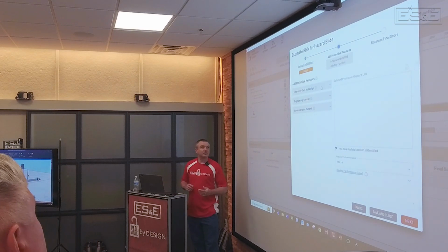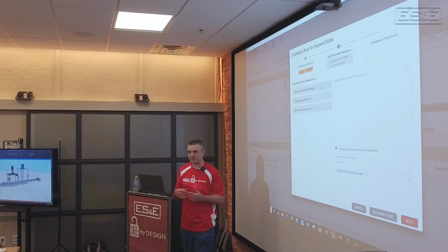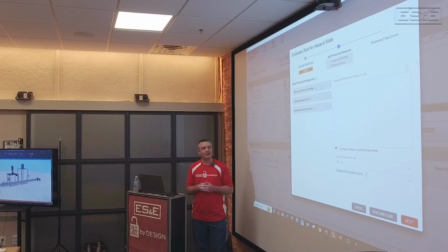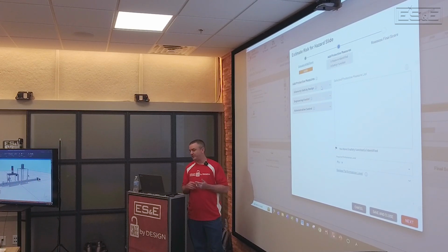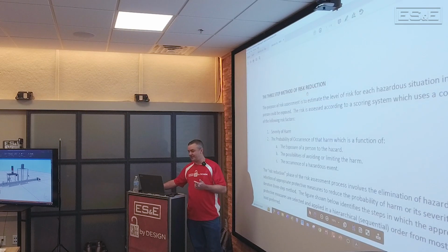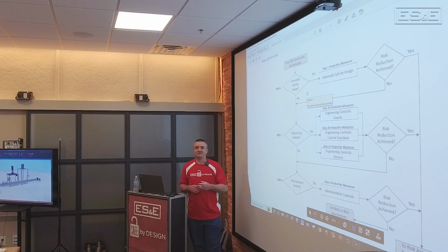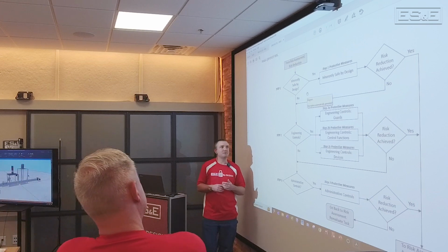So now that we've evaluated our machine with no guards in place, or what we're proposing, which is what Henry's got drawn up here, I think we want to discuss how we want to solve the problem, because obviously that's not a tolerable risk, what we developed there. So your opportunity for protective measures, if we look at the standards, is basically we can design it out. Right, which is probably the most desirable way to do it, right? That is definitely the most desirable way.